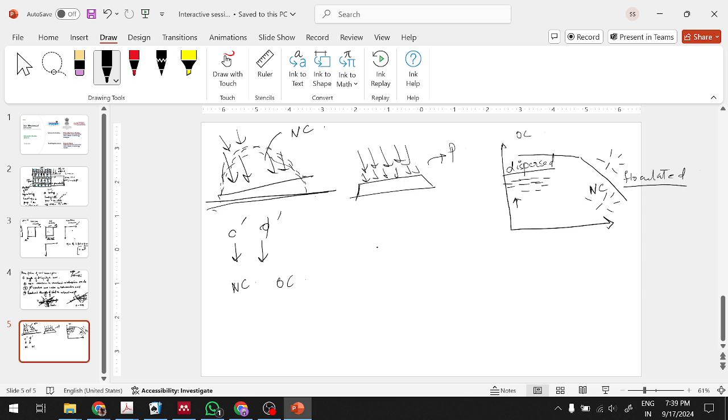So when we move on towards critical state soil mechanics, and we talk about the critical angle and these advanced failure criteria, like the modified Cam-clay and everything, we talk about a critical angle up till which, for example, you have an NC clay, it will show high volume reduction while shearing, and OC clay will show an increase in volume with shearing.